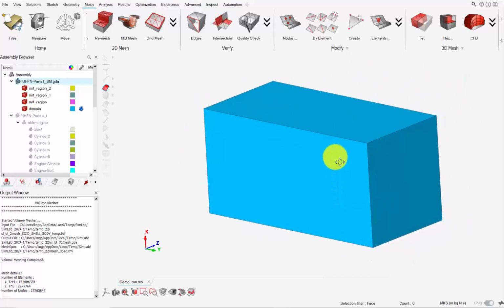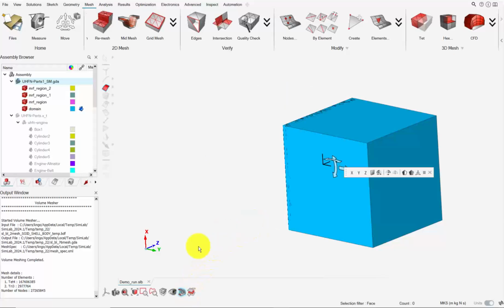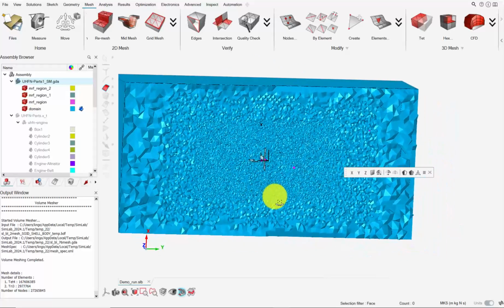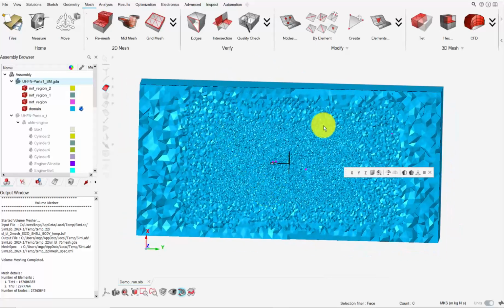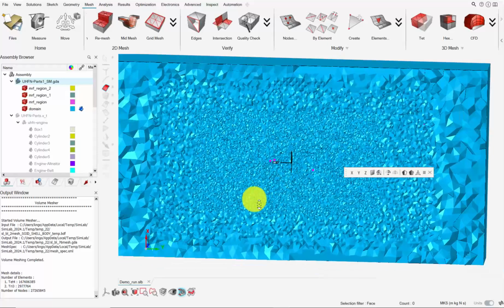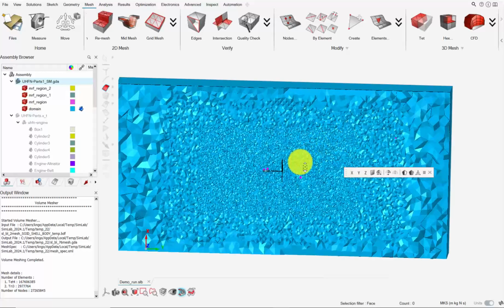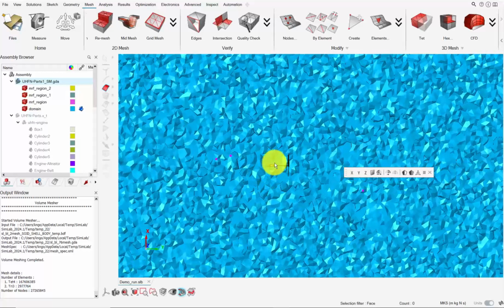When the mesh has been completed, we can turn on the cross-section to take a look at the tet elements. Let's turn it into the Z normal direction. At a glance, we can see that the regional mesh control is respected really well, where we have a coarse mesh size outside and then further refined inside.